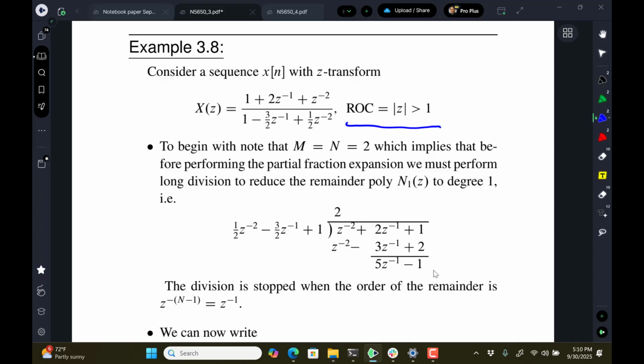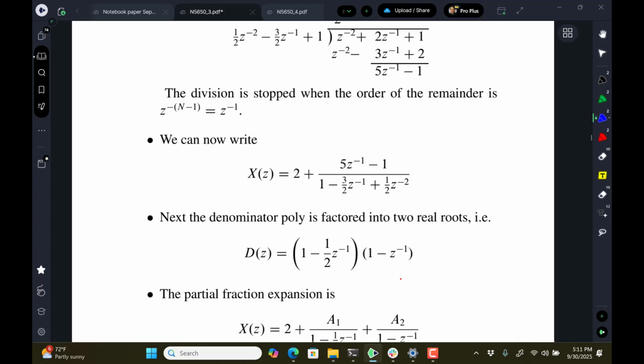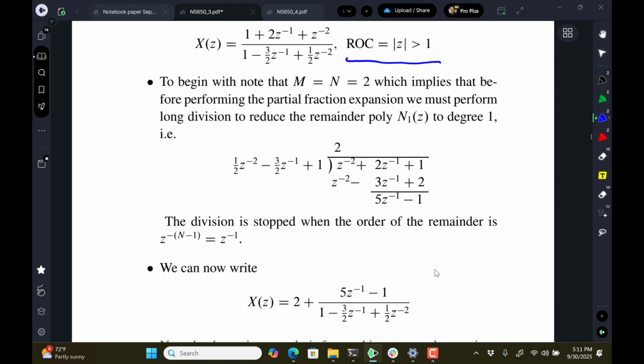Correct. Does that make sense? Because that is setting a boundary on the region of convergence. So there must be at least one of the roots of that denominator at 1 or minus 1 or j1 or minus j1 or something like that. We'll get to that in a second. Right now, though, we just do our line division.